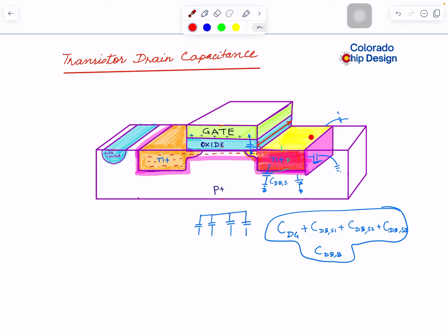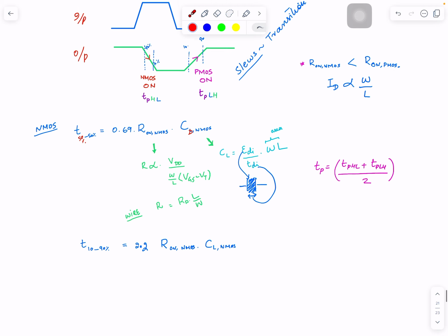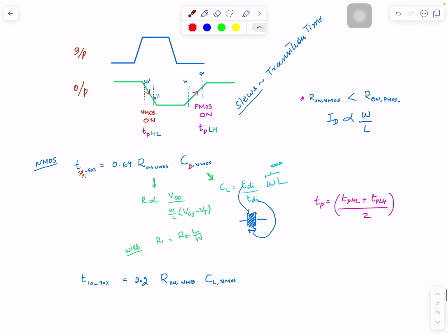If the whole area is smaller, there will be less capacitance. So those cells which are bigger to have a smaller delay, their capacitance will increase. And sometimes we see what the dominant factor is. As W increases, the current also increases, or the capacitance becomes a problem. So you need to think of those.